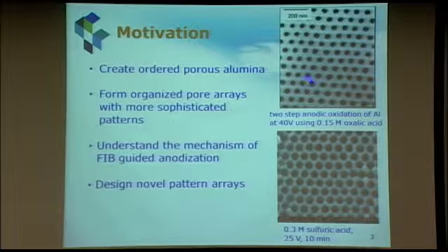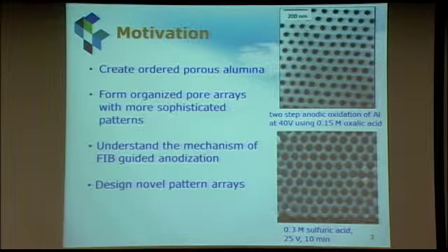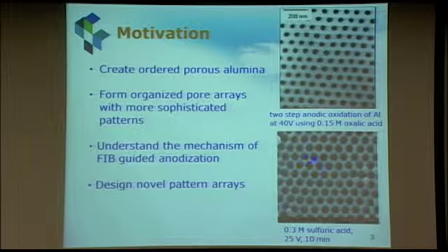And this actually became very popular about a decade ago. It's called a self-organized process because these pores, if you apply the conditions right, automatically form this hexagonal structure. And we have done this for different conditions like this one. It's for different acids. By changing the acid in your solution, you can change how large the pore is and how far apart these pores are. But fundamentally, they are all hexagonal structures.